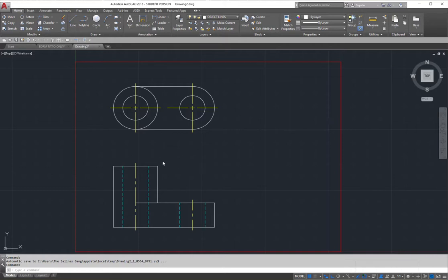So when you see this right here, you know that your layers, as we set them up, the line type and the line weights are different for each one of those layers, but we don't really see the difference right here. When it prints, you will see the difference, but you don't see it right now. But if you wanted to see your line weight, and you said, okay, let me just make sure that I can see it, I have to go right here to my hamburger and make sure that I check anything that it's check marked right here, it's showing up right here.